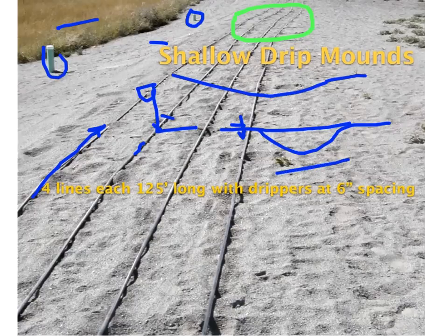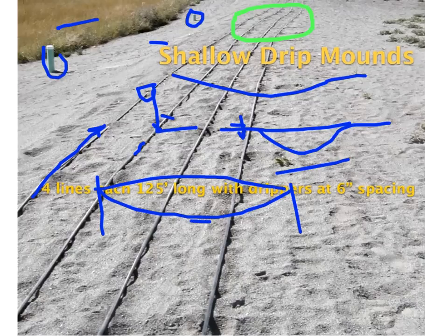But you don't want your drip line to be like this, because with the manifold here and the manifold here, you'll certainly get more water here. But it's okay if it's like that, because then when you switch off, it'll drain that way and that way into the supply and flush manifolds. So you can live with that, you can't live with this.